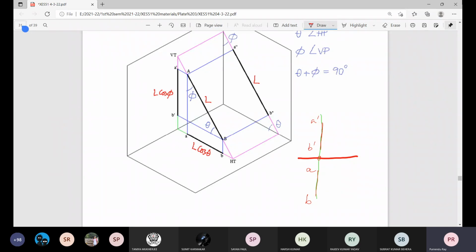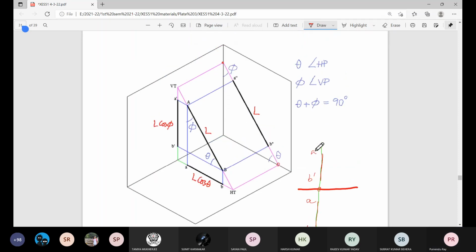But if you think in some other manner, you see from this side and we consider the line itself projected on the pictorial plane. Then extend the side view to meet the ground line. Extend the side view to meet this axis there. What we get then? We get the side view of this HT and VT. Corresponding plan point will be HT corresponding to this, and corresponding to this elevation point will be the VT.